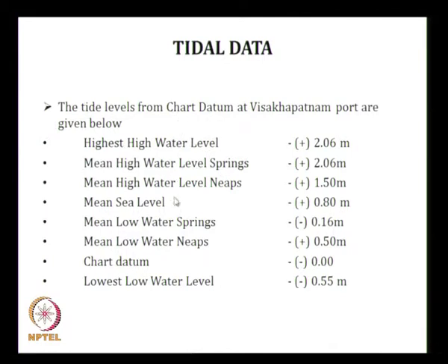These are the various levels. You have the highest high water level, mean high water spring, mean high water neap, mean sea level, mean low water spring, mean low water neap. There is a chart datum, there is a lowest low water level. These are the various levels which are to be considered.